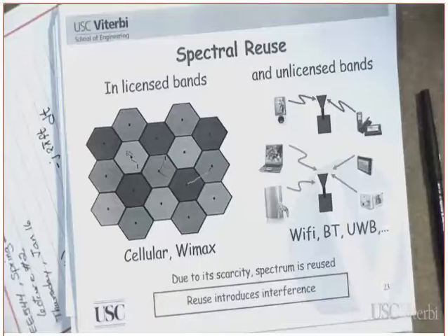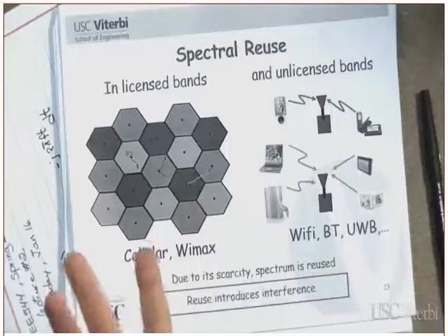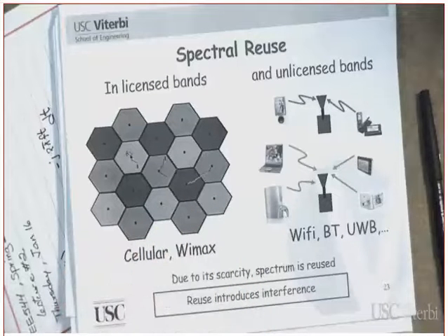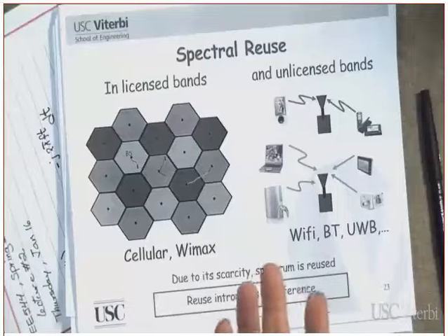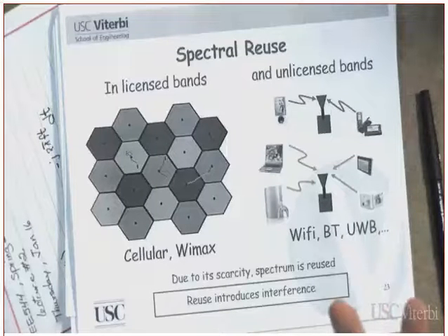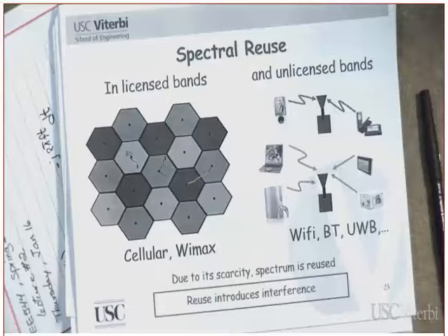Why? Because first of all, it's transmitting at what? At the gigahertz range for the satellite, depending on whether it's the Ku band or the Ka band. But in addition to that, the signal has to go through roughly 35,000 kilometers to reach the geosynchronous satellite, which means you need to pump enough power to reach the satellite. Did you get this or not?